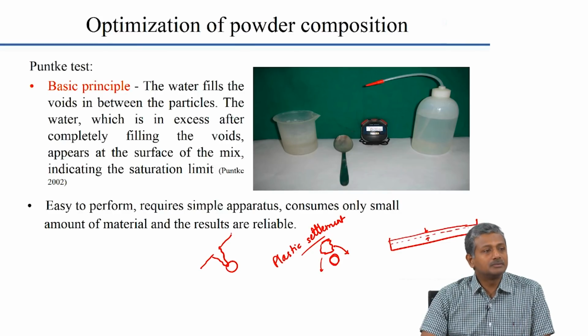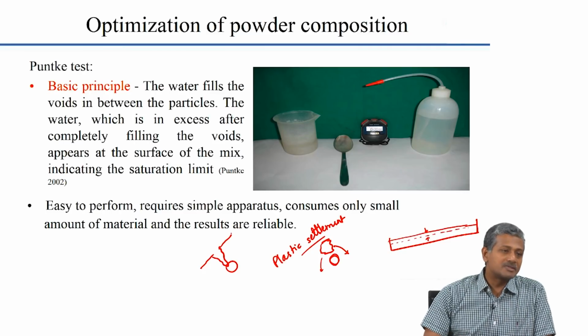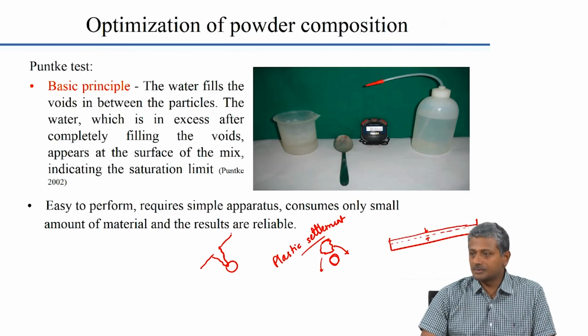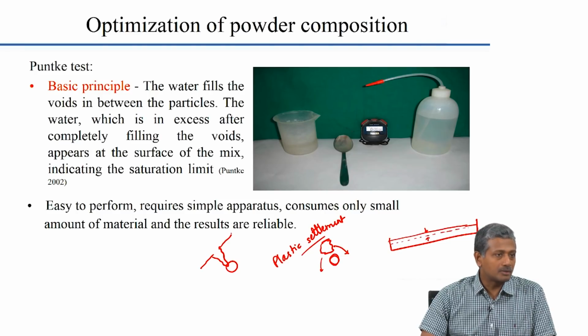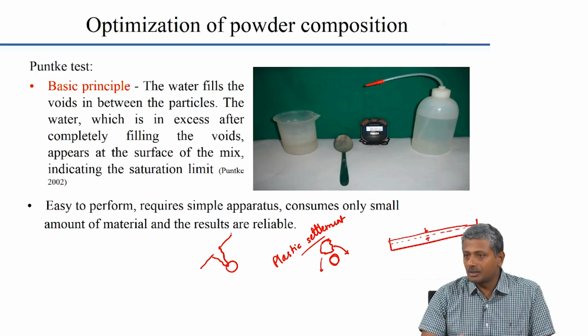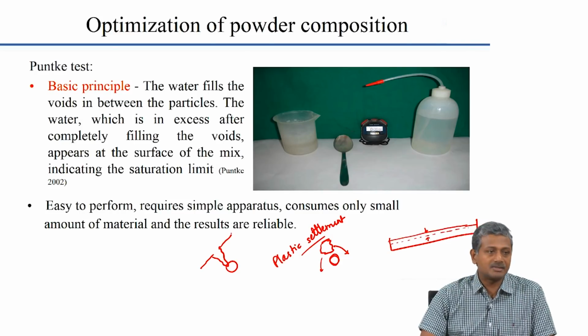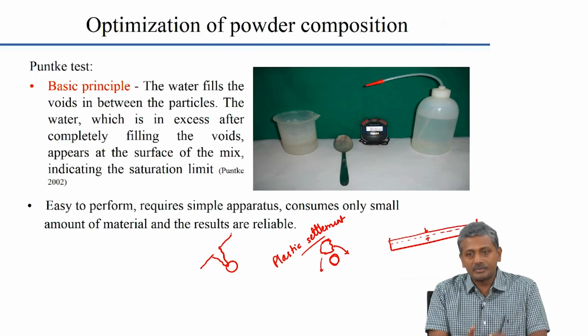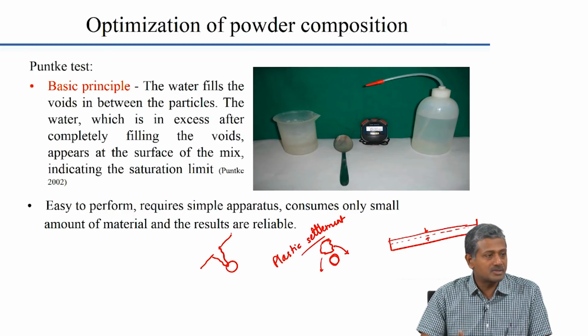What do you do then? For the strength, how do you design SCC for strength? Again, you assume the same water to cement ratio relationships that you typically get with ordinary concrete, right. Yeah, that is a good starting point. You may not get the same answer, but at least for a start, when you want to design SCC, you consider strength depends on the water cement ratio, and for a particular strength you choose the right water cement ratio and design your SCC based on that.